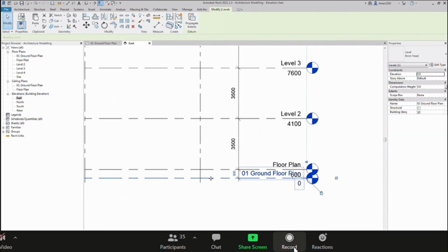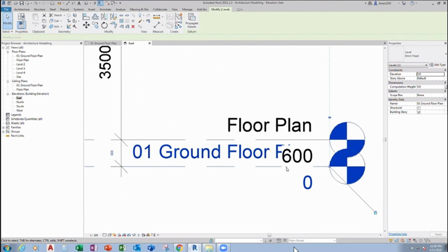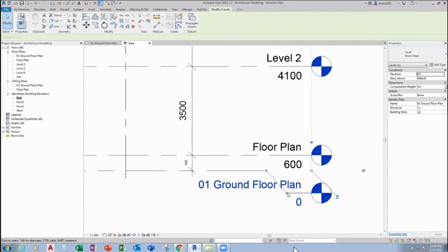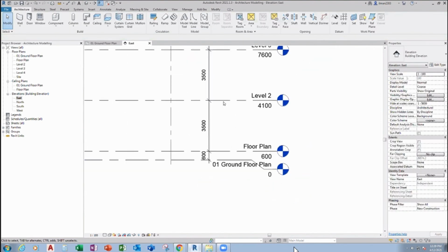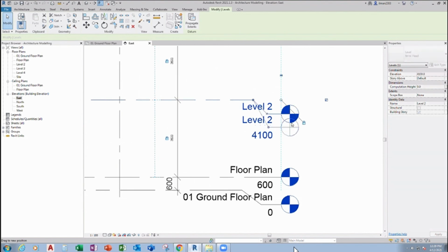Ground floor plan, you must click your ground floor plan first and zoom in, and you find that there is a zigzag icon, the add elbow. You click the add elbow, and automatically you can adjust whenever you want. Can? So you click the grid first and you find the zigzag elbow or add elbow, and you click it. So you can freely adjust.